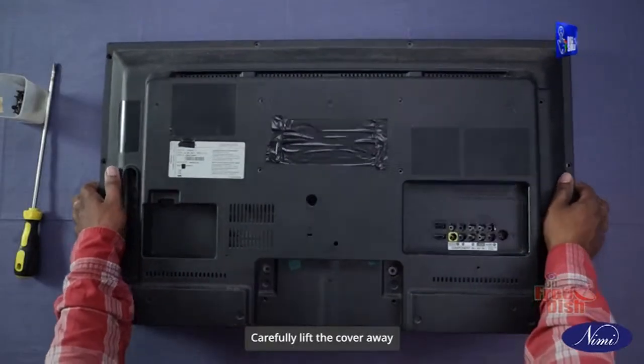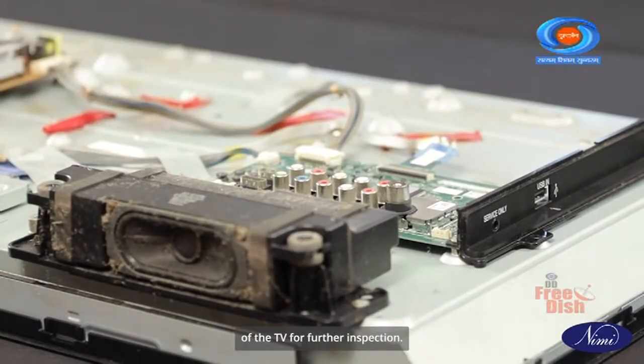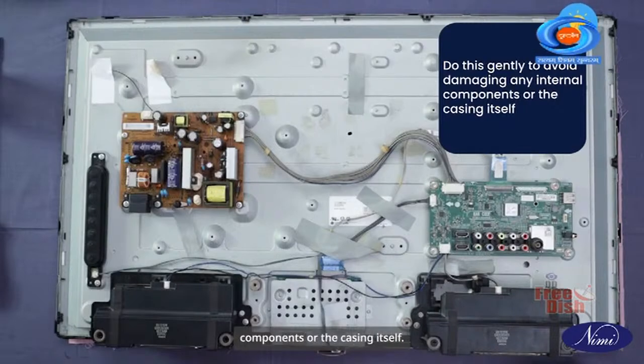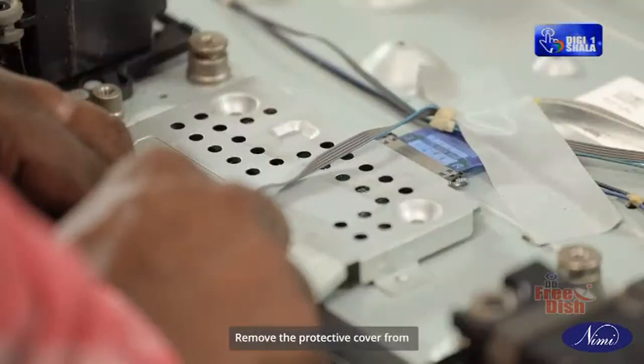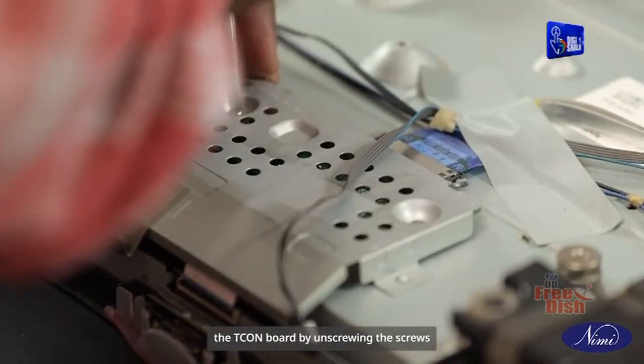Carefully lift the cover away to expose the internal components of the TV for further inspection. Here is a safety tip. It is advisable to do this gently to avoid damaging any internal components or the casing itself. Remove the protective cover from the T-con board by unscrewing the screws.